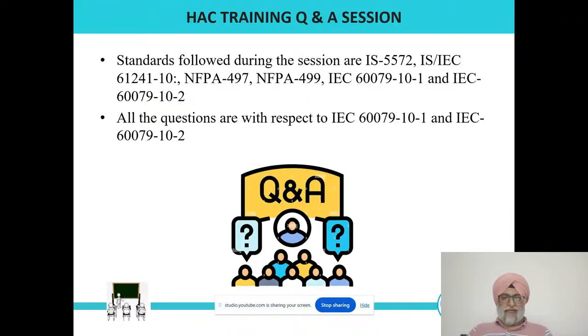During the international webinar, the standards which we explained were Indian standard, NFPA, and IEC. The Indian standards for gases and vapors was IS 5572, and for powder, IEC 61241-10. The NFPA standards were NFPA 497 and 499, one for gas and one for powder.